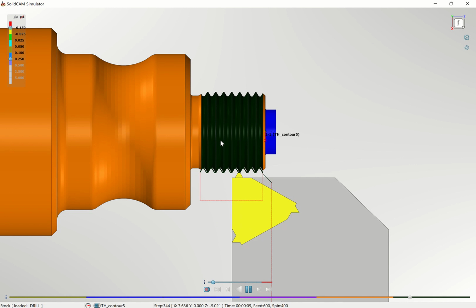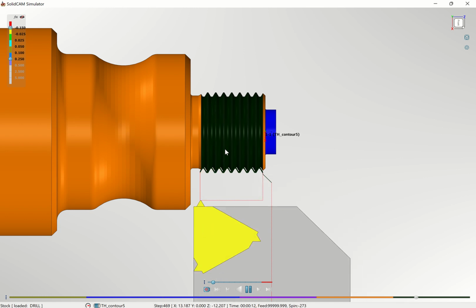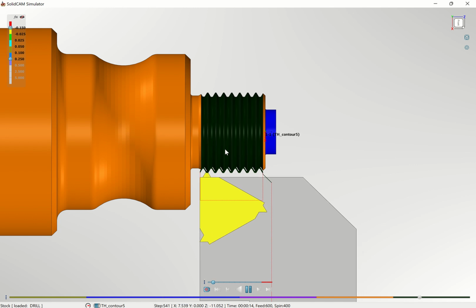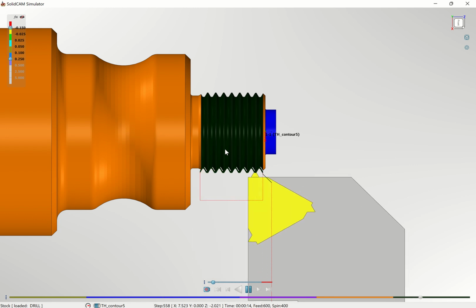In case you see somewhere there's material left, ensure that the tool you're using for turning has the radius that corresponds to what it's supposed to do. But if it leaves material, then you can even use a grooving tool to do turning. Because your grooving tool is square-sided, or has a simple radius, use the one which has a radius of 0.1 to do your groove turning, so that it doesn't leave excess material on the part.